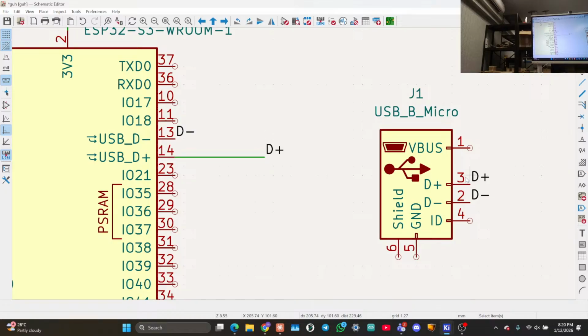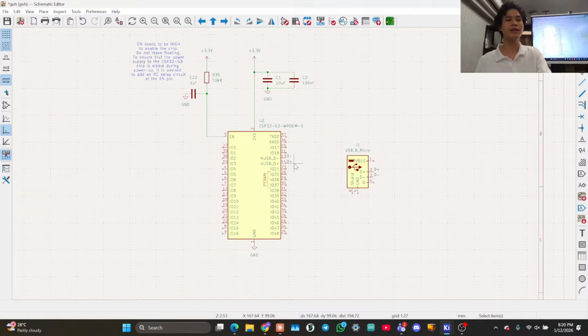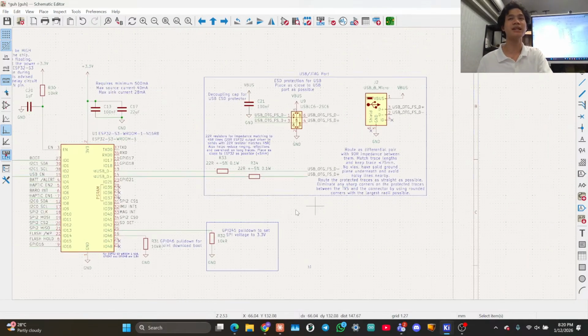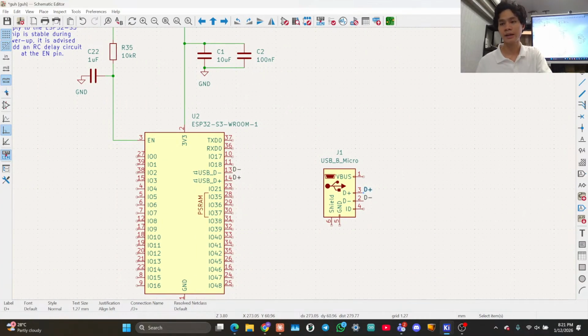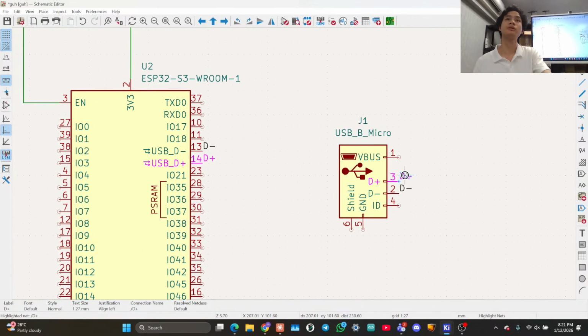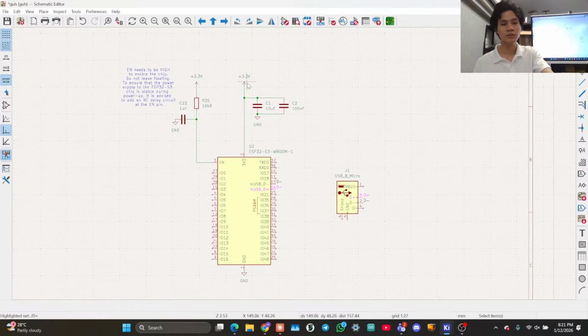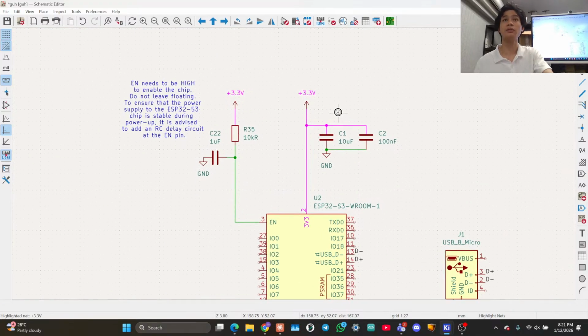Okay, great. So I was showing you the highlight net function. It's annoying to read all of your net labels, especially when you've got as many as I do. So you can click a single net label and go to highlight nets. So highlight net and then click it and it will highlight all of them blue. I can do this for literally any net. I just escape to stop doing it. Here's 3.3 volts. So it highlights the wires as well.